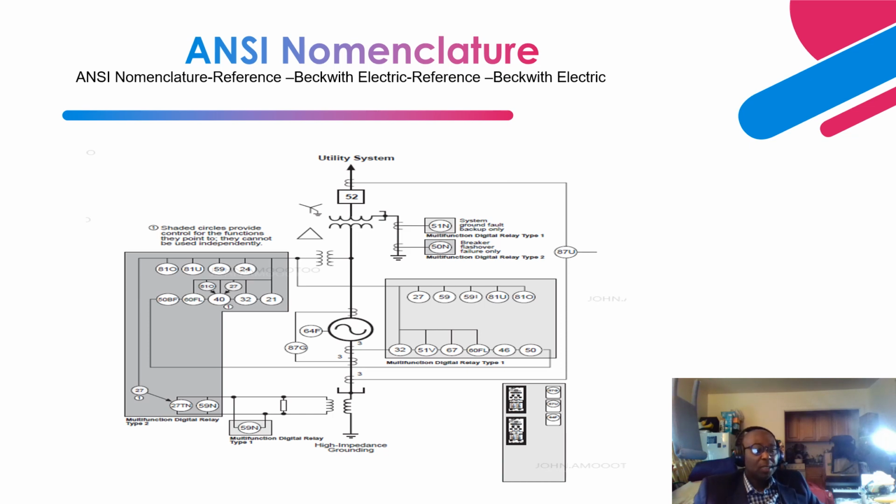Next, all these protection relays can be a multifunction digital relay, a microprocessor relay, right? So you can have all these protective elements in a single relay. We have the 81O, like I indicated. This relay operates based on over frequency of the generator, when the turbine generator is operating in an over frequency condition.